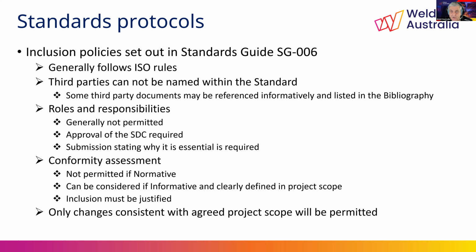This was especially the case where we were able to demonstrate conformity with ISO provisions. Examples there include your welding supervisor, the welding engineer in limited cases, welding coordinator, welding inspector, and there's about 20 different titles. Other examples include where there is a statutory responsibility link within the work health and safety regulations used in Australia. Now, conformity assessment cannot generally be included unless the standard is specifically drafted as a conformity assessment document, for example AS 3920, which is used in the pressure equipment industry. Compliance with these types of standards is usually informative rather than normative.